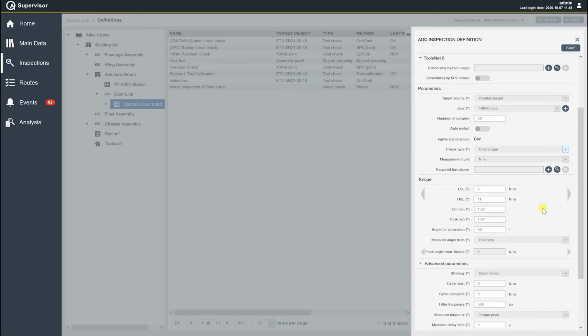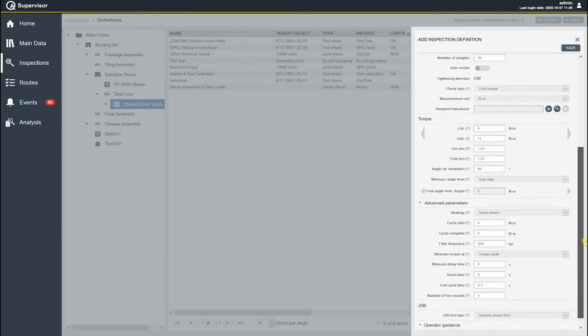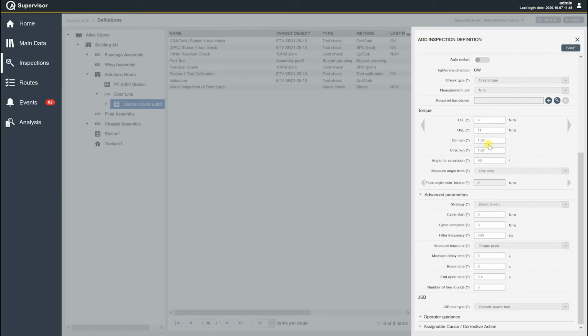The joint information that I was referring to has come in, and you can see it here. If I toggle between, you can see my target and my plus-minus percentage in this case. And you can see my upper and lower spec here. These are all values that we can change if we need to. If we want to pull something a little bit different, we can change the default CM and CMK values here.